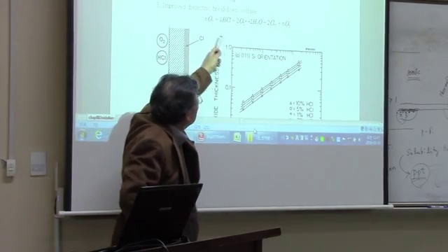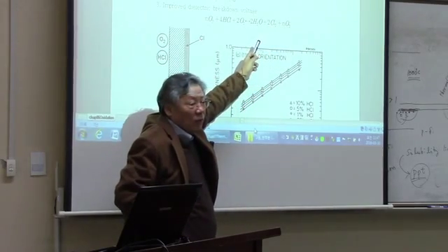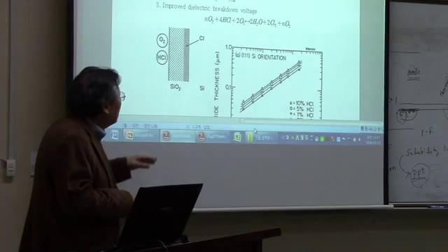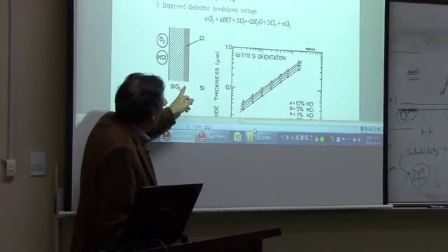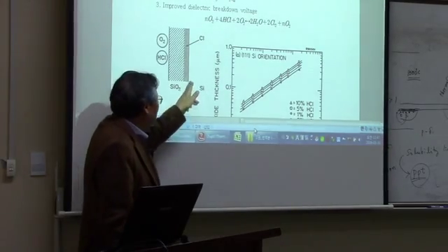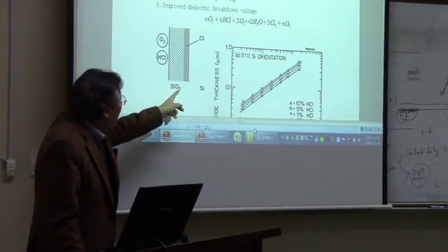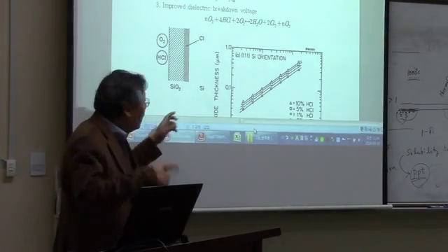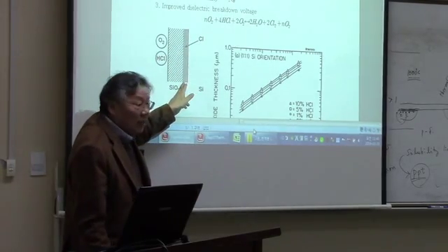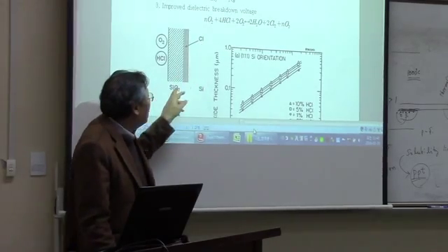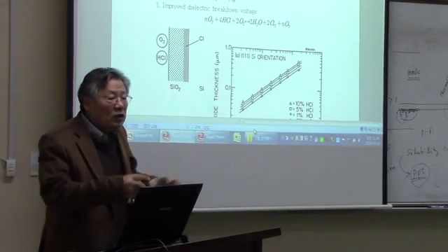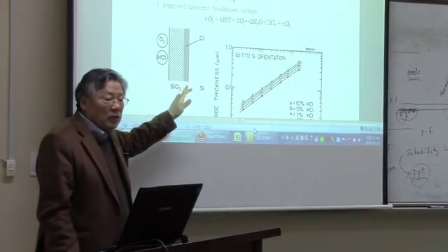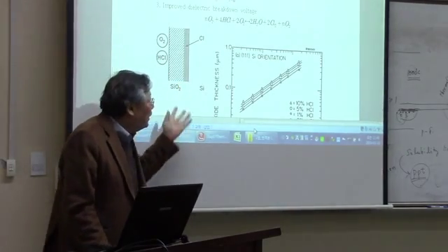Then it's very much like wet oxidation. We form water here, and then we have Cl2 gas as well. And it turned out that the Cl minus ions are going to accumulate at the silicon oxide side of the silicon oxide and silicon interface, as you can see here. And this is the location where the fixed charges, which are the positive charges, okay, are located right here. So this Cl minus, which is accumulated at the interface, is going to annihilate the fixed charges, which are positive, so that it also decreases the amount of interface trapped charges. So that's why it is preferred in the industries.